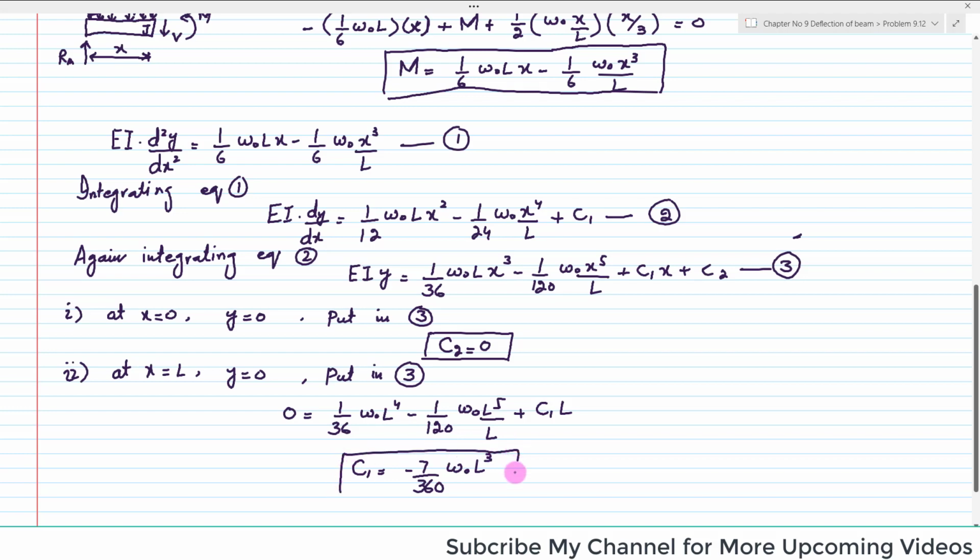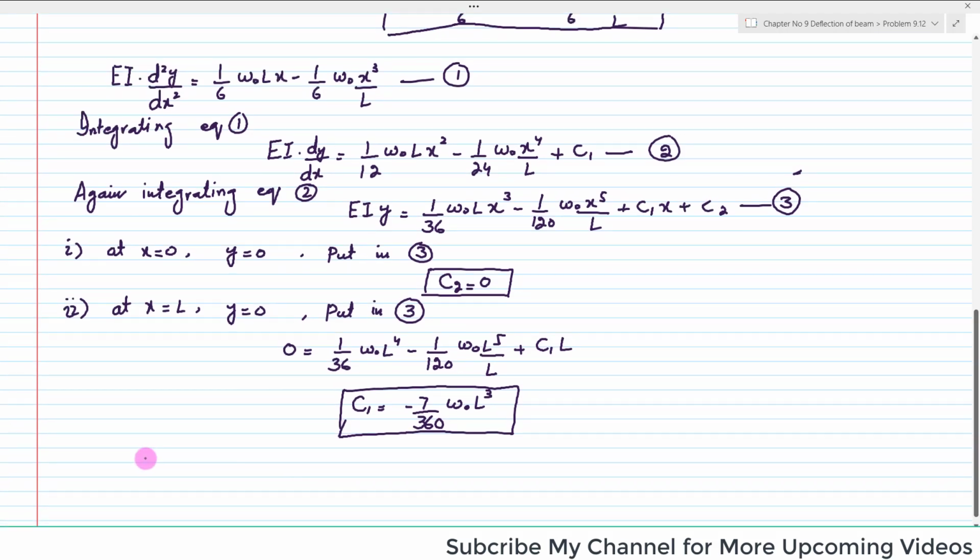Now you can put the values of C1 and C2 in equation 3 in order to get the equation of the elastic curve, or the equation for deflection. So put C1 and C2 in equation 3. So equation 3 becomes equal to EI y, and again divide both sides of this equation by EI.